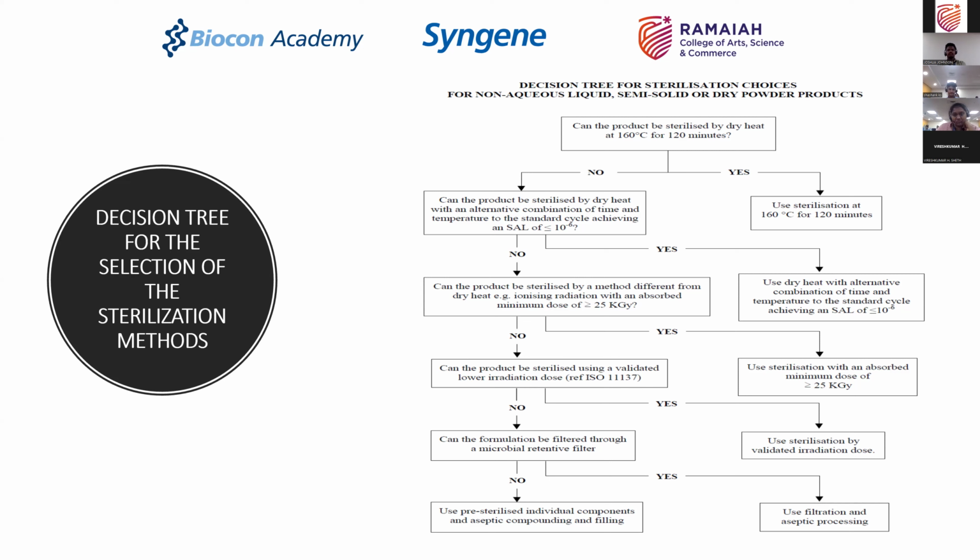So when you are especially dealing with powders, and there are a lot of products which are powders, especially a lot of your beta lactams and cephalosporins, which are all powder products. Also, there are certain complex injectables, called microspheres today, which are dry powders that are reconstituted before administering to the patient. And in all such situations you have powders, and either you have to use aseptic processes or you have to use the radiation methodology or heat.